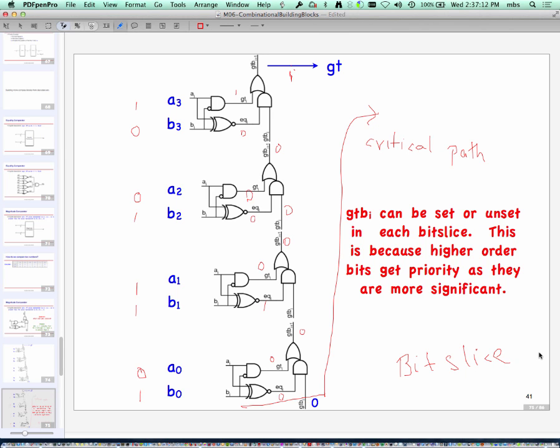I'm taking my design, slicing it into 1 bit, designing 1 bit and just replicating it. It simplifies the design process considerably. You design once, optimize that 1 bit very carefully, and then gang it together. Whereas if you don't do a bit slice type design, your workload goes up, although quite possibly you may end up with a better design that way.